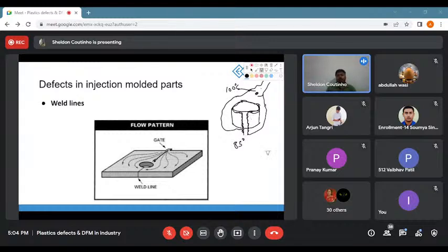Now let's consider that your plastic will solidify at 50 degrees. So this temperature over here is not enough for it to solidify, but it is also not hot enough for it to homogenize and mix and form a proper homogenized surface. Because of that, these outer surfaces will stick together. They will have a certain amount of strength, but it will never form a homogeneous or uniform looking surface.